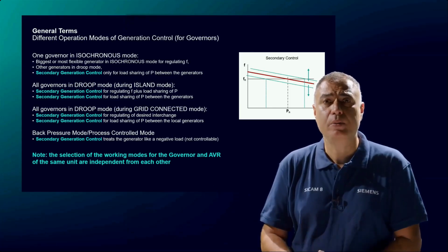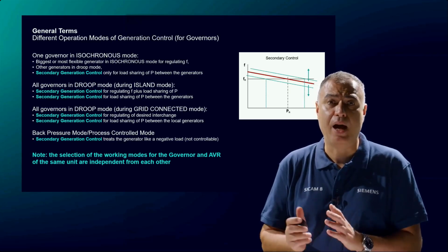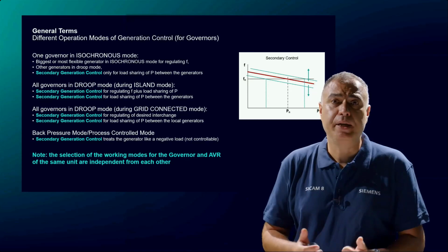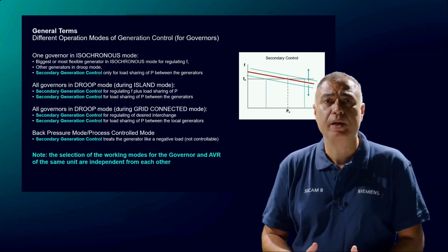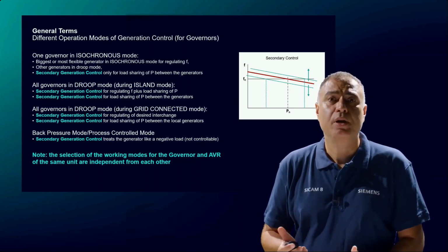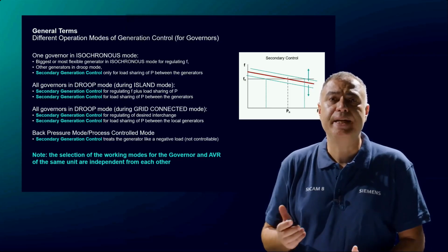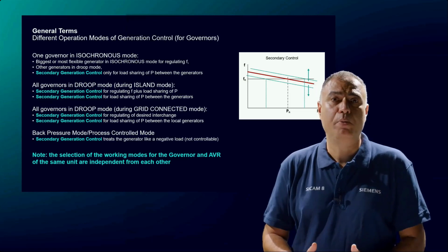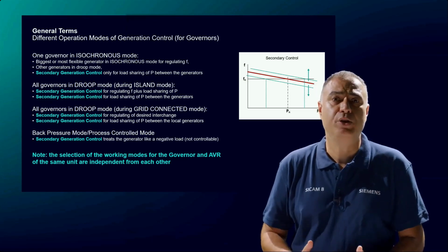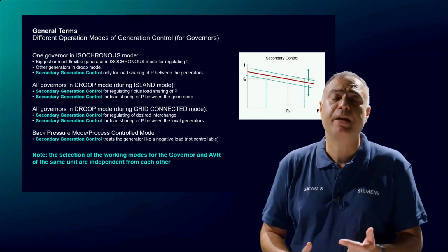In this scenario, the major advantages of our secondary control system are by shifting the droop curves of other generators up and down, the SICAM generation control enables the generator working in asynchronous mode to stay in the middle of its regulating range. By shifting the droop curves of the individual generators, also predefined load sharing can be observed.